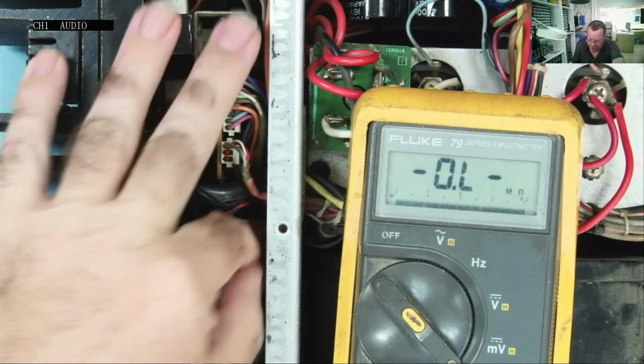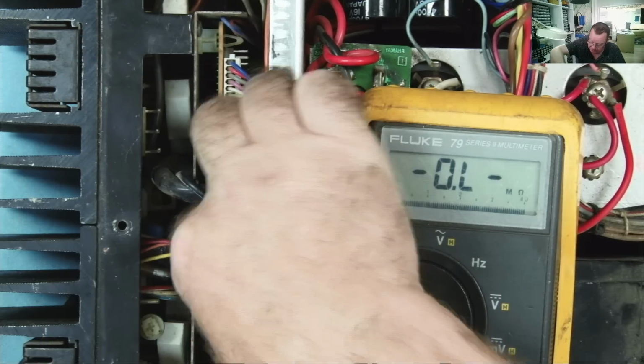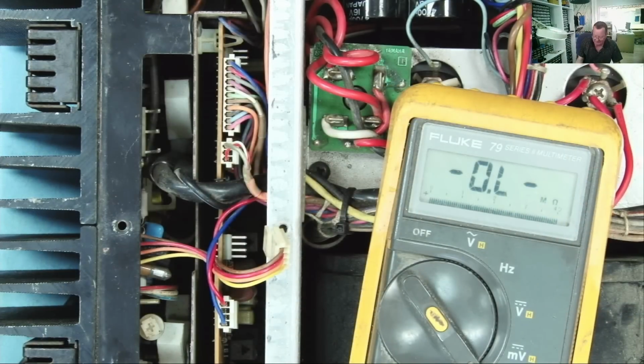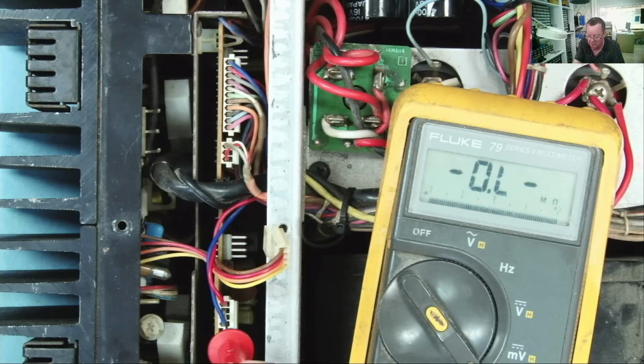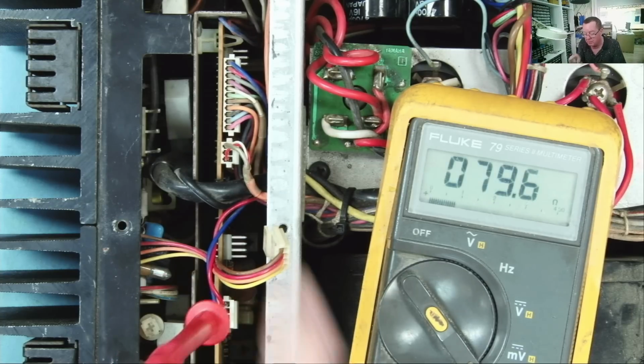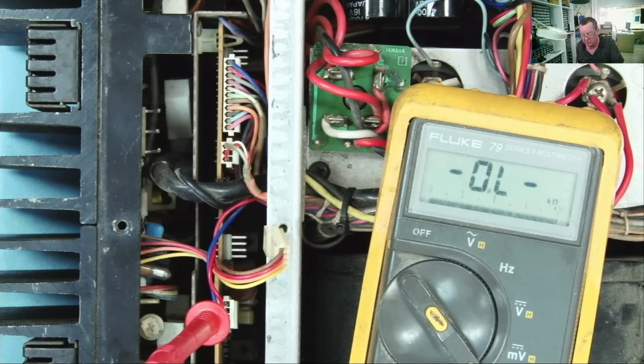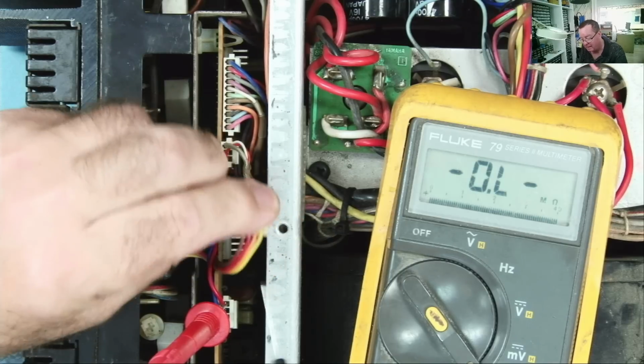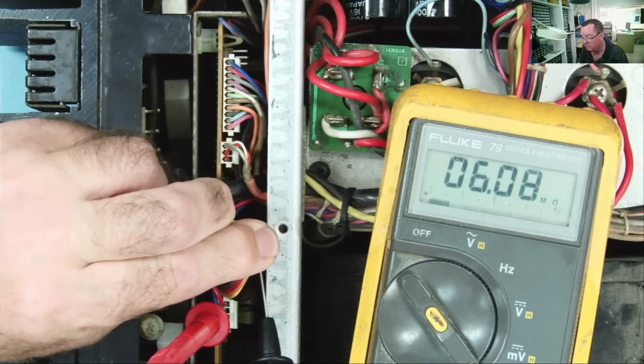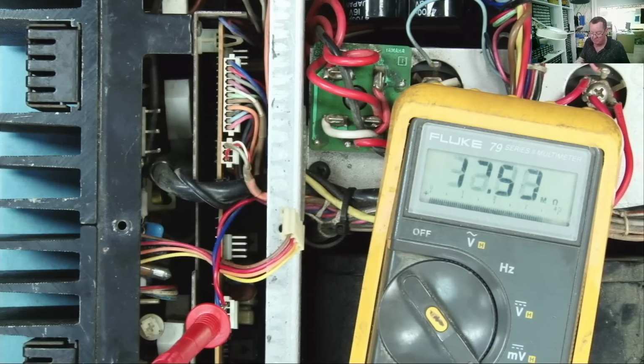So that goes to a little plug down here. I should be able to get to it. There it is. Right, where's the short? Well, let's look on the red one again. Is it gone? No, it hasn't gone. So the fault is on this board. The fault is on here. If we go to the yellow wire now, it's 60 meg. So fault is definitely on this board, okay?